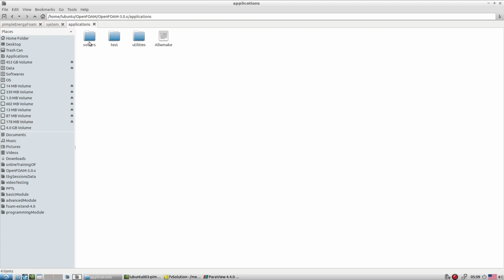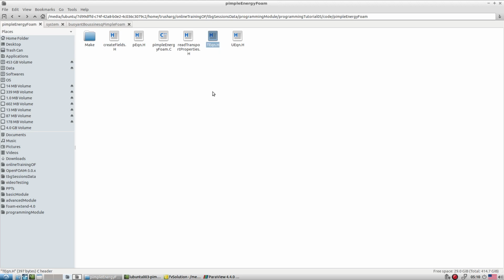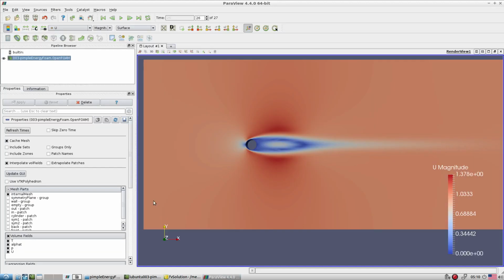We went to the applications solver area, and first copied incompressible pimpleFoam. Then we went to heatTransfer and the Boussinesq-based pimpleFoam. From there we added the T equation and plugged it inside our area, and then slowly we modified step by step, and then we came to know that